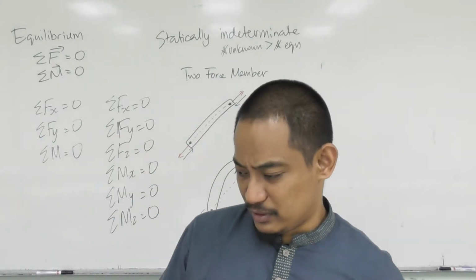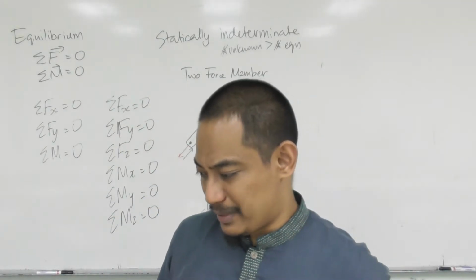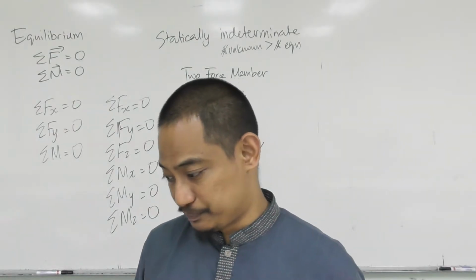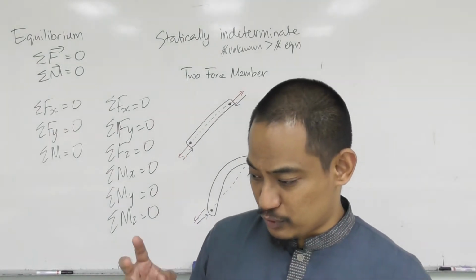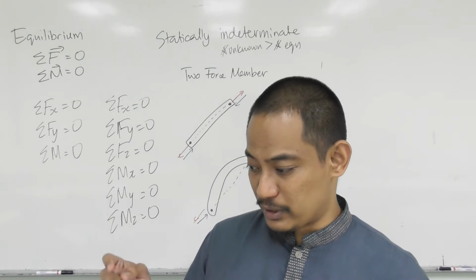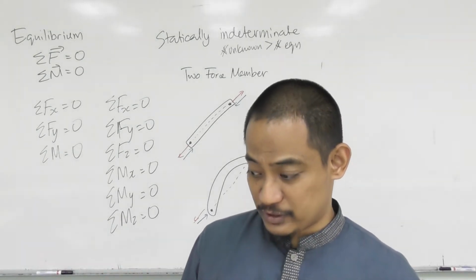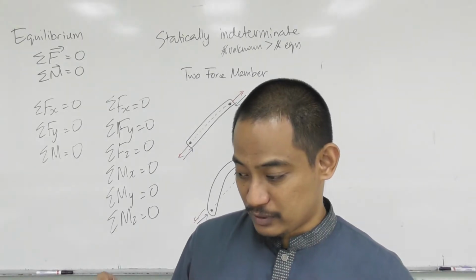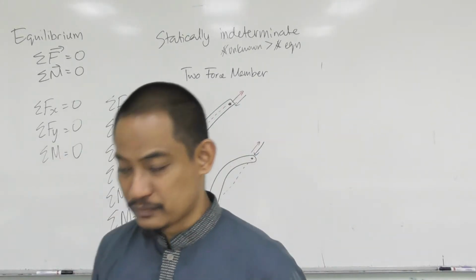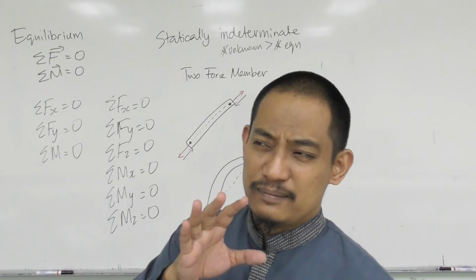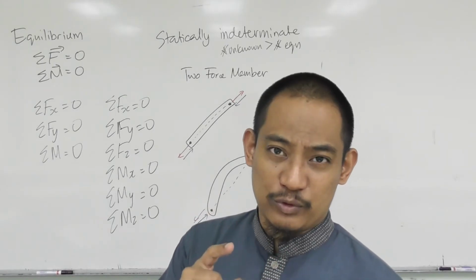The second important note: the order in which you apply the equations may affect the simplicity of the solution. For example, if you have 2 unknown vertical forces and 1 unknown horizontal force, then solving summation of Fx first allows you to find the horizontal unknown quickly. That normally comes with practice.